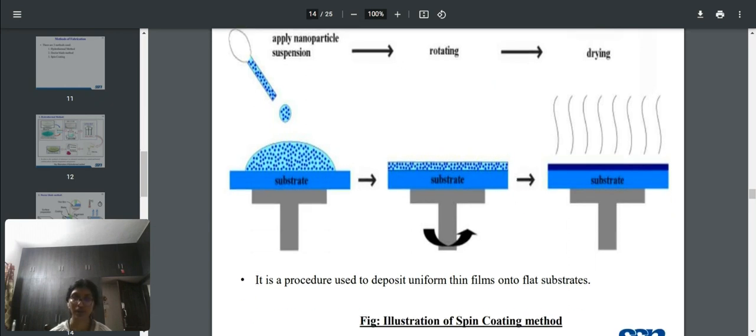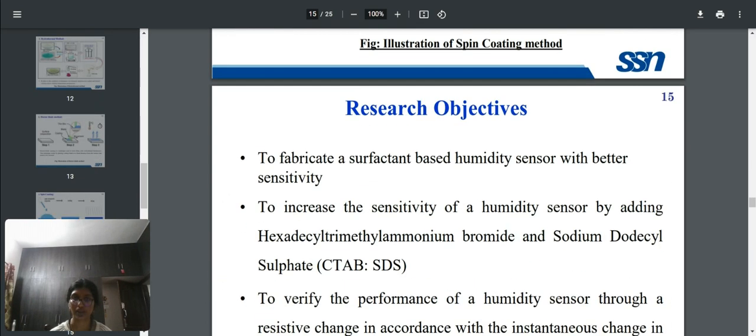After the ZnO-NiO nano layer is formed, PEDOT:PSS solution is added by a micropipette, which will act as the P side, and this substrate along with the ZnO-NiO nano layer acts as the N side. PEDOT:PSS stands for poly 3,4 ethylenedioxythiophene polystyrene sulfonate, which is used for its thin surface and high conductivity.